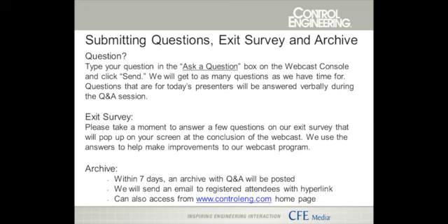In terms of wireless, we'll probably have many of those. We'll have to see what happens on the ISA100. It was designed specifically for the industrial environment, so it has a lot more security built in and a lot more capability for running routerless with mesh networks. So it'll be interesting to see what happens there, but I believe that we are going to be talking about Ethernet and the various Ethernet protocols for a very long time in this area.